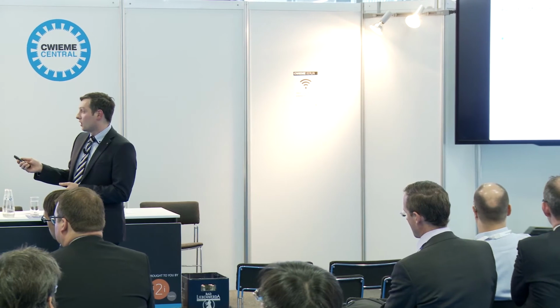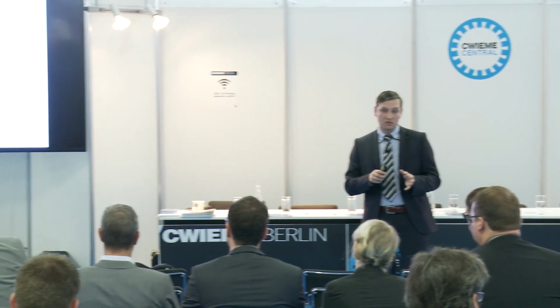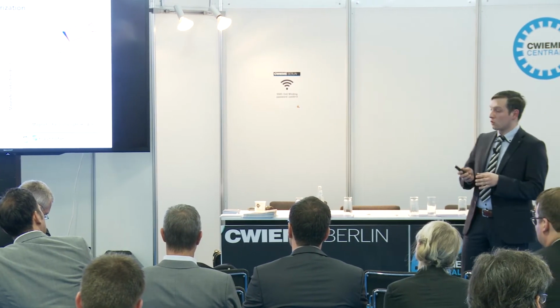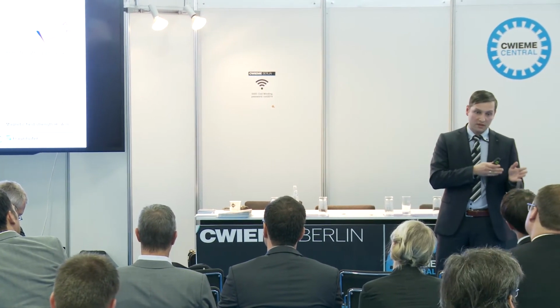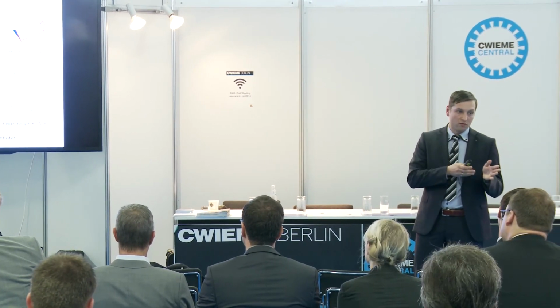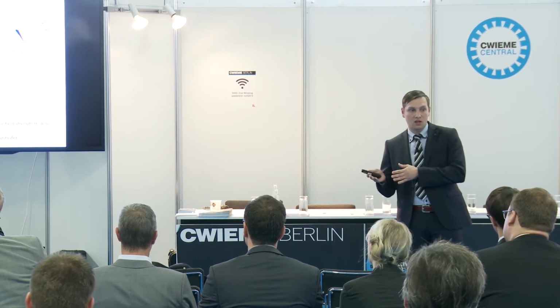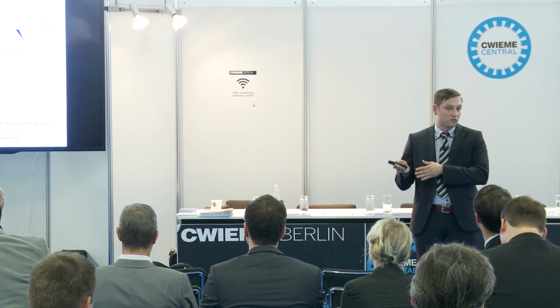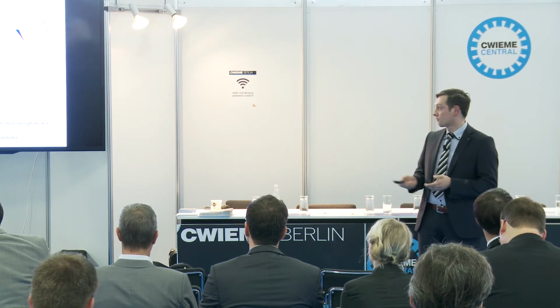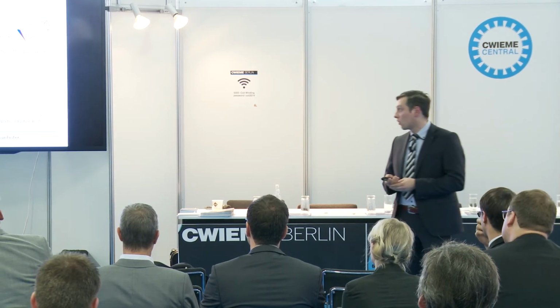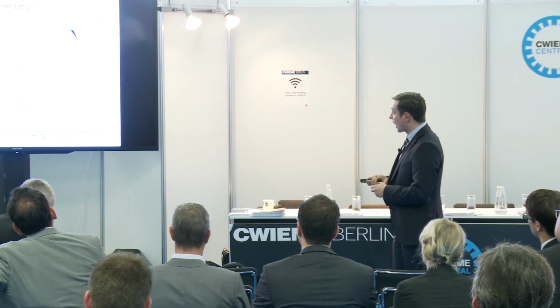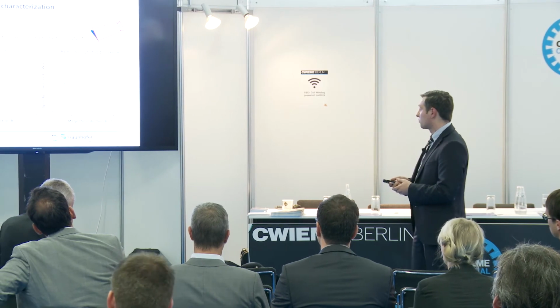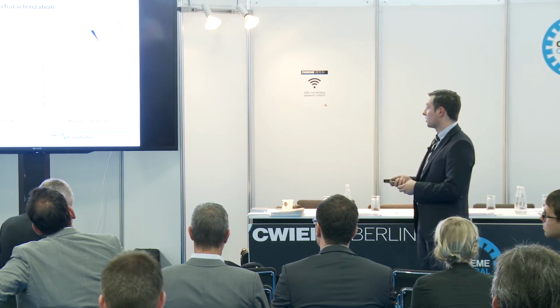On the right-hand side, I wanted to show how flexible this process is. You can adjust your process to achieve perfect magnetic behavior. Then the cycle time is the same as conventional cutting, or you can increase the cycle time, but then you will have just the same magnetic properties as conventional cutting. Same holds for the specific core losses. Here again, remote cutting achieves pretty good results.